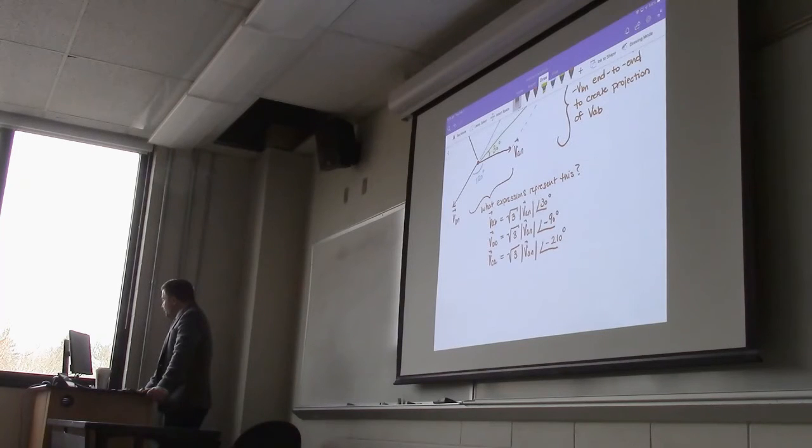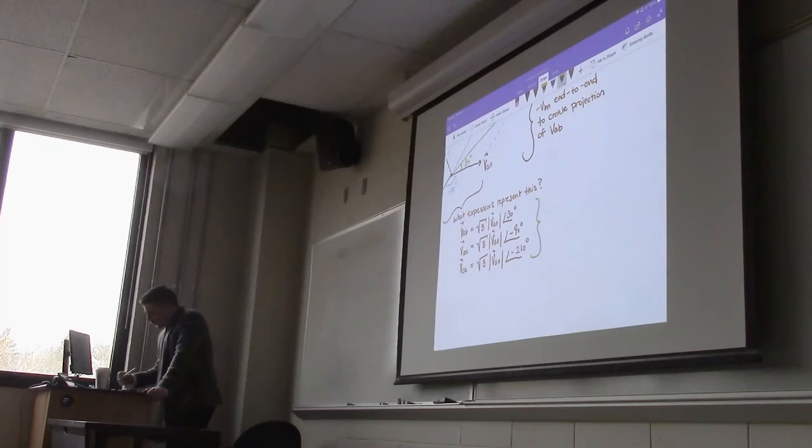Okay, so the last thing I'll write here is that for each phase, the line-to-line voltage is a square root of 3 factor longer than the line to neutral, and has a 30-degree offset with respect to that individual phase, right?